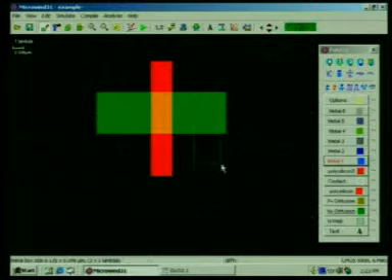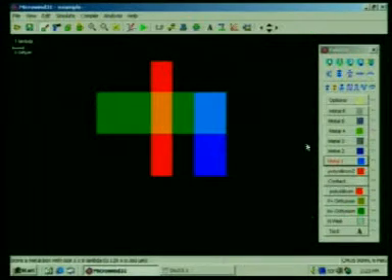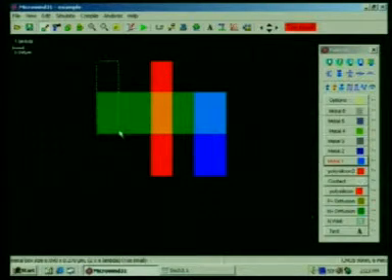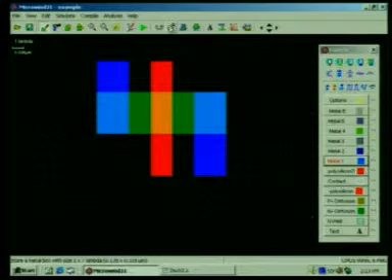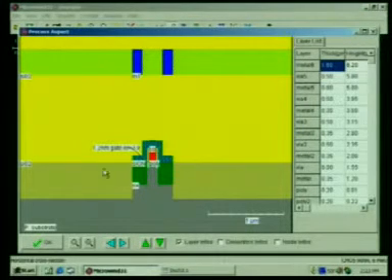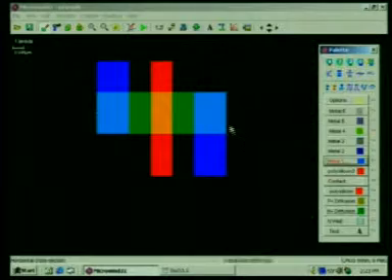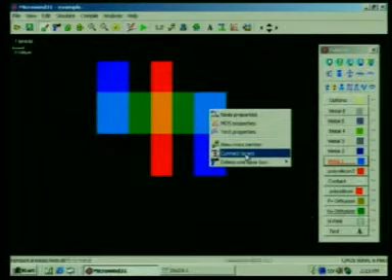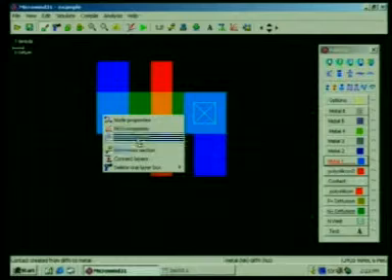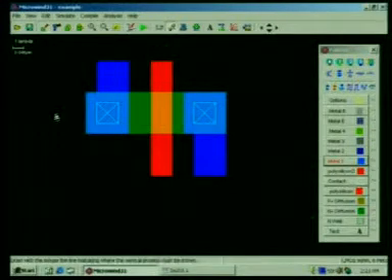Okay. And then you need some metal layers to show the gate and to show your drain and source region, this one, and like this. You can check out the 2D view. This is the 2D view. This is the strain technology I have already discussed with you. We need to put some strain here, so that we can control the mobility of the atoms. And after that, you have put these metal layers, and now you need some wires only. So, you need to put some contacts. So, just right click contact layer. Now you can check out again the 2D view.